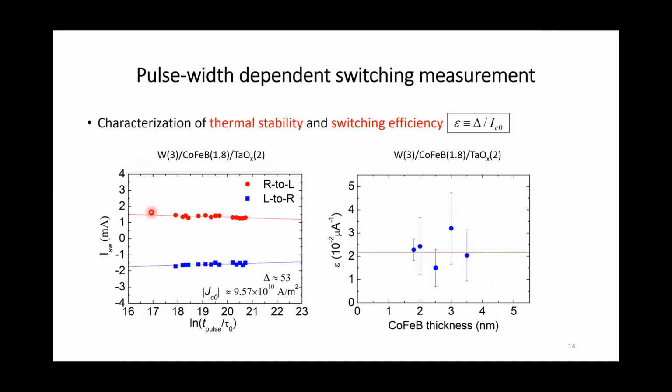So the thermal stability here, maybe as Qiming just asked earlier, and as I mentioned, the switching is actually maybe just a part of the ferromagnetic layer, because we were dealing with a very large patterned film. So all I can say is that a part of the ferromagnetic layer has been switched. I'm not sure if it's full switching because we haven't done any longitudinal mode measurement. But judging from the AMR, the resistance difference, it is probably not a full switching.